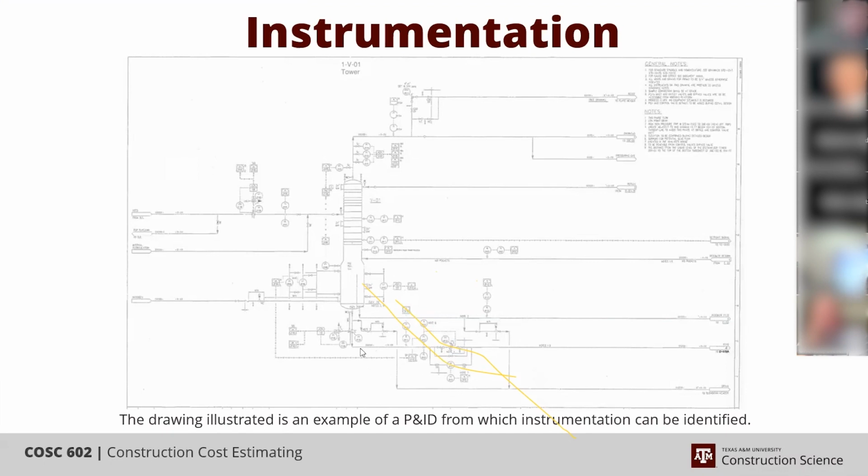So then you see it connect to another one, like the one at the top on the outlet. This looks like a degas column or distillation column. So those 3 indicators right there are all sending a signal back in house. Yeah, so this is back in the control room, I believe, and that's the element. That's a temperature element. That's a temperature transmitter. And so if you looked at it, it'd be TI or TE, temperature element. TT would be temperature transmitter, and it's sending the signal back to the control room.